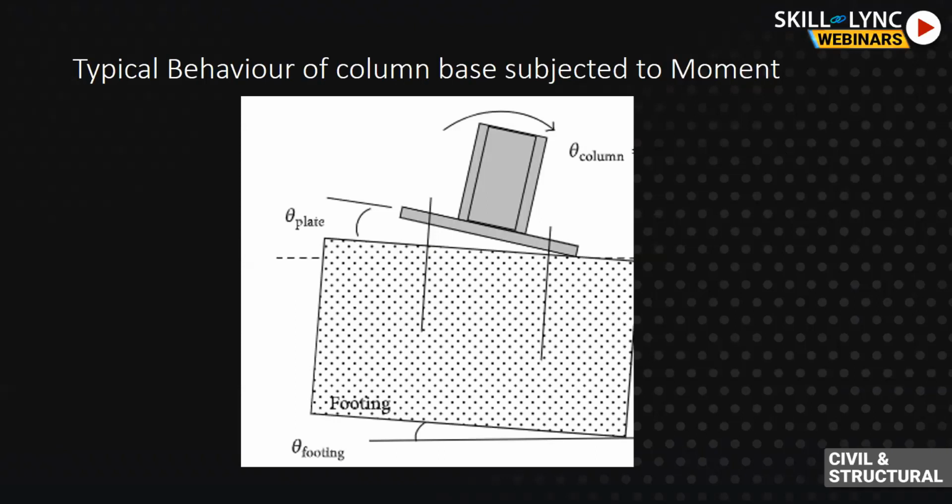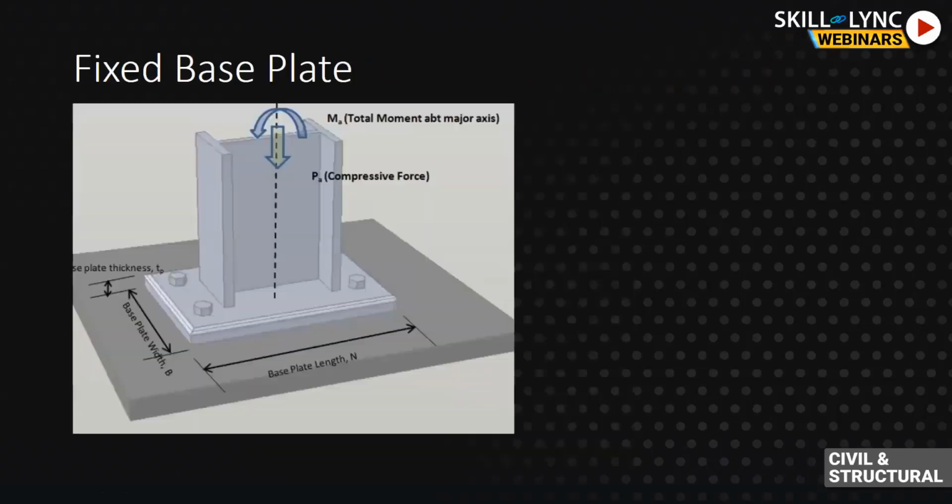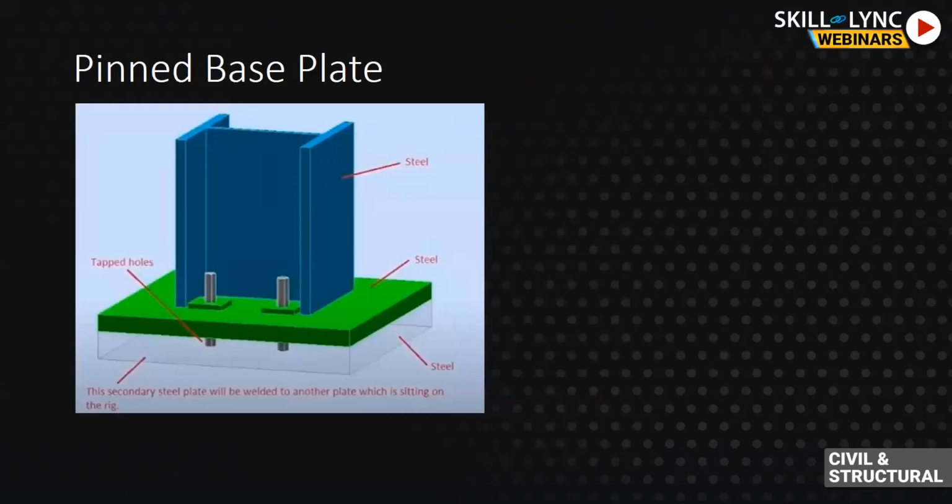As it is not going to be subjected to this, we don't require anchor bolts at such extreme distances from each other. We don't want any moment resistance in the pinned base plate, so we don't want to unnecessarily increase the size of the base plates. So we need anchor bolts to anchor it to the foundation, but we don't need them at such extreme distances. So how will a pinned base plate be detailed? Let us see. Here on screen, you see a typical detail for a pinned base plate.